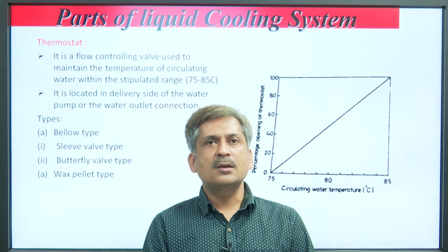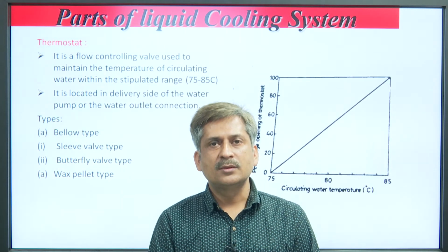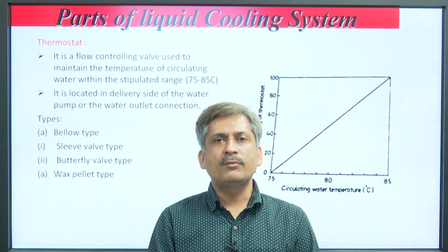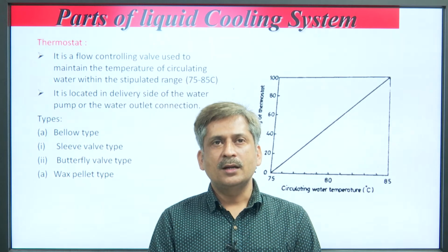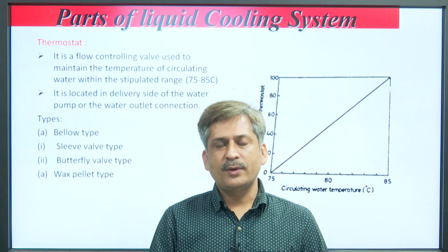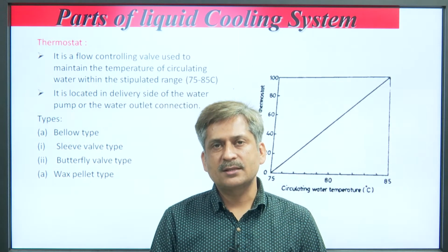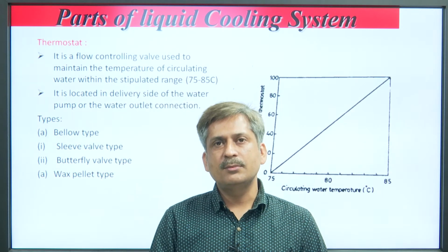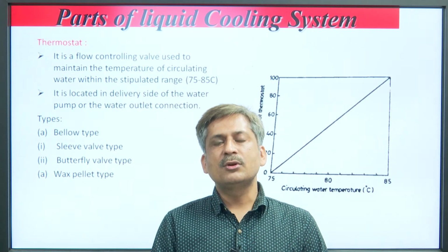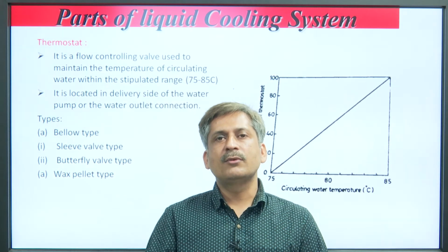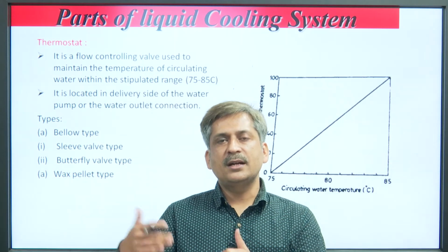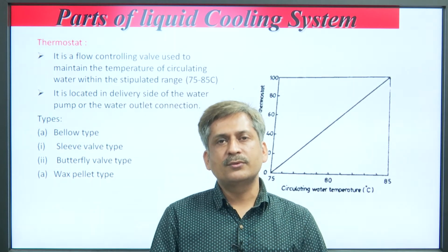Now, come to another very important part, the thermostat. The thermostat is a thermostatic valve, which means it operates as a function of temperature, at a particular range of temperature. When cooling is not desirable, just like when you are starting your vehicle, there should be some heat also. Cooling is desirable after some interval of time. When that temperature is achieved, the valve opens and the circulation of water starts.